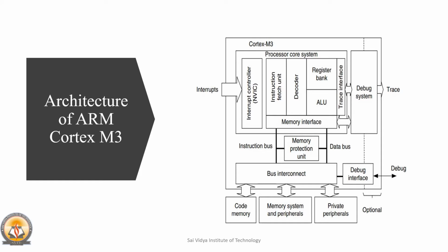It is a memory mapped system with a simple fixed memory map for up to 4 GB of addressable memory space, with predefined dedicated addresses for code, SRAM, external memory devices, and internal and external peripherals. There is also a special region to provide for vendor specific addressability.